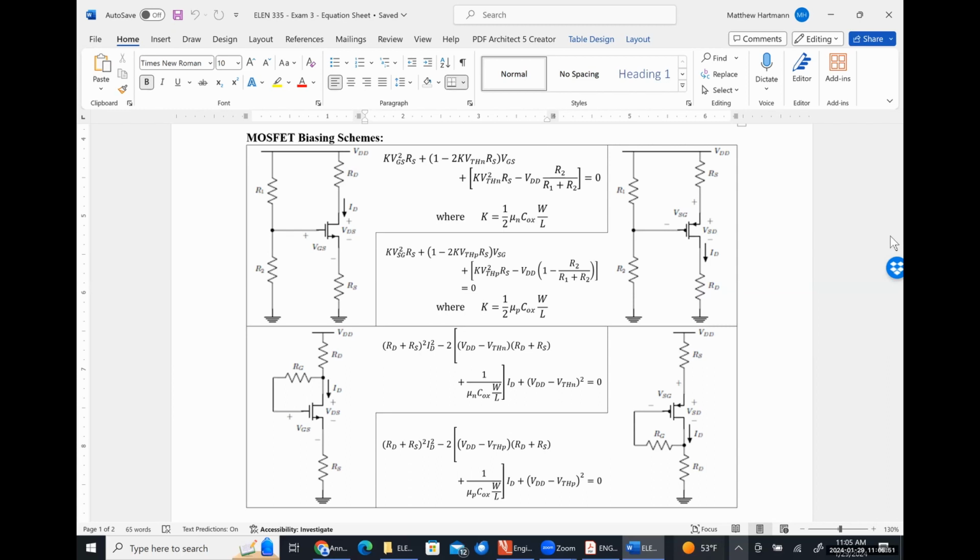And I can't make you come up with a numerical solution for anything in the triode region, because you'd be solving a system of equations where some of those coefficients are for squared terms. So your calculators literally can't solve that system. But layout similar to this: NMOS device, associated equation, PMOS device, associated equation, NMOS device for self-biasing, associated equation.